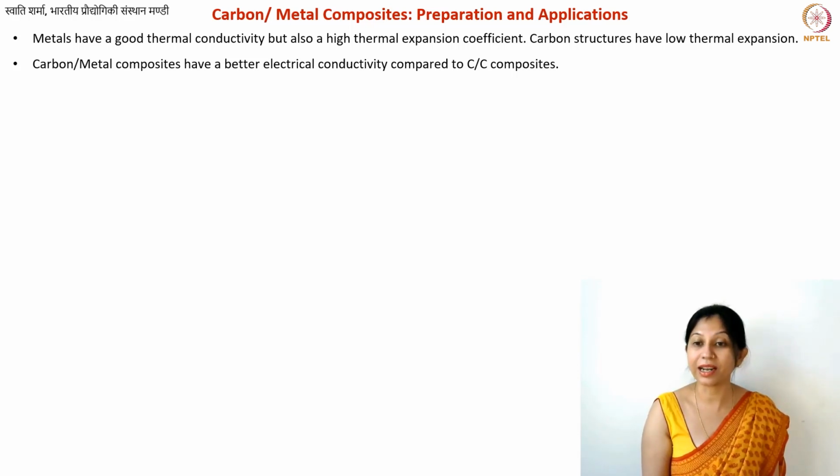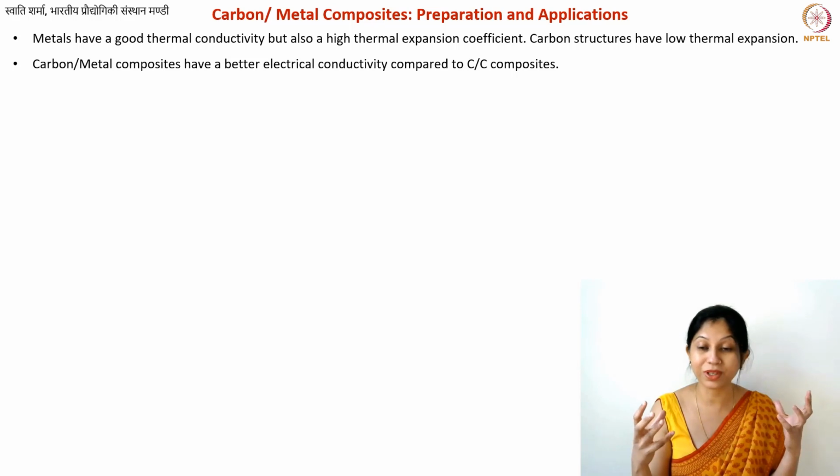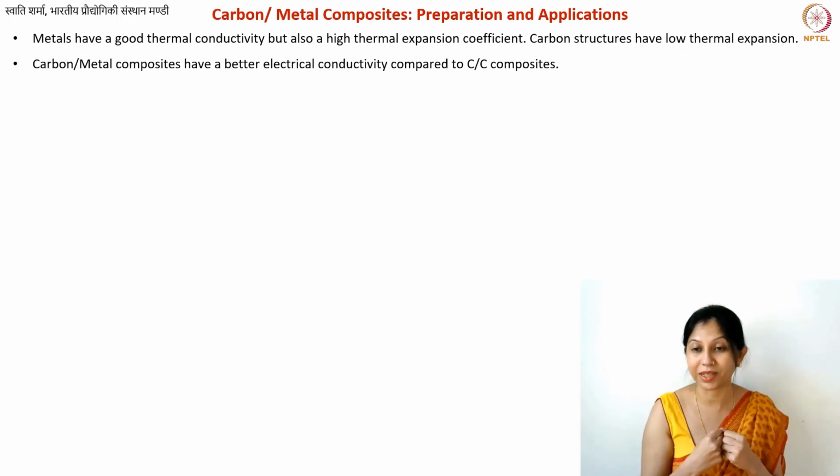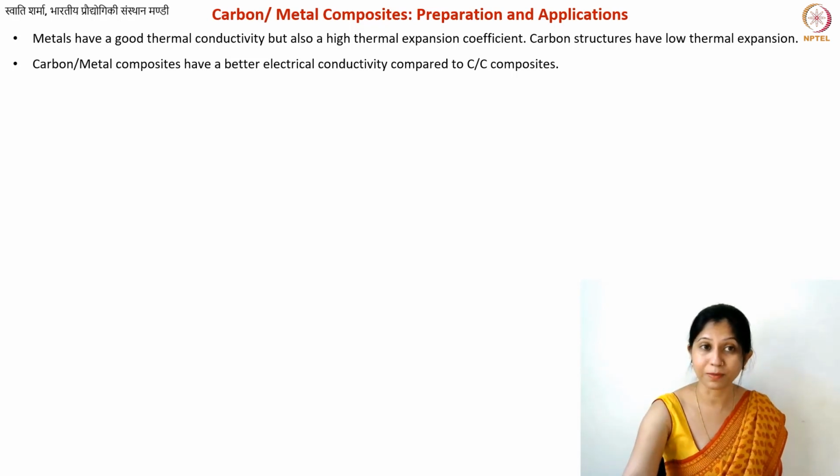That is unfortunately not the case with metals, or most of the metals. Of course, we do make these high performance alloys and super alloys, but in general, if you want to ensure that your metal does not expand so much at higher temperatures, then what you can do is add these carbon fiber like materials, carbon materials, because we know this very well that our carbon materials have a low thermal expansion coefficient and they are very good at withstanding the thermal shock.